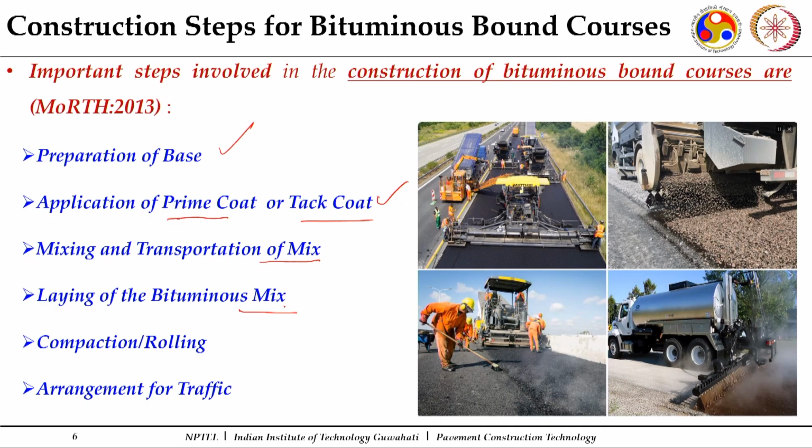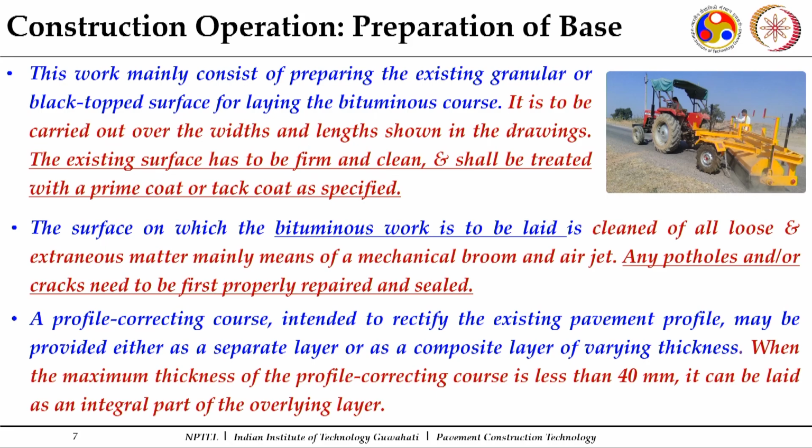There we need to lay it properly, and then compaction and rolling has to be carried out. Finally, a time has to be given, a window has to be given, because they are laid at higher temperatures, so the temperature comes down before the surface is finally opened for the traffic. So, we will discuss these aspects individually.